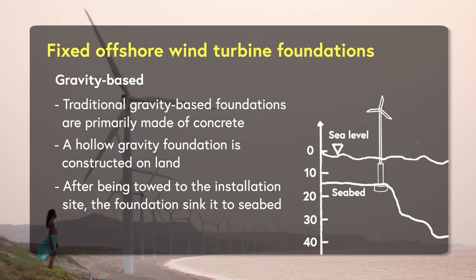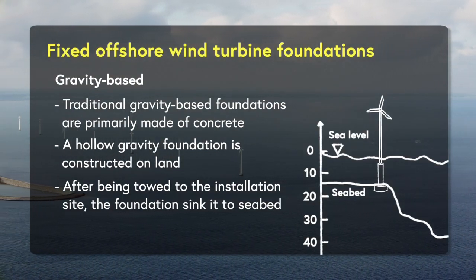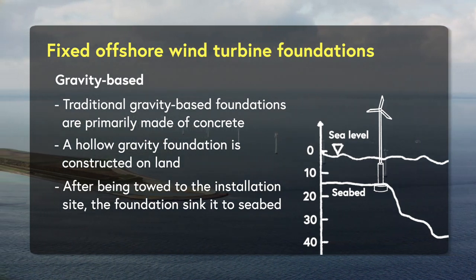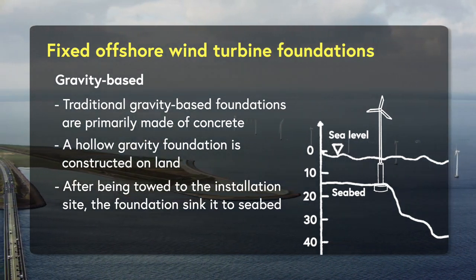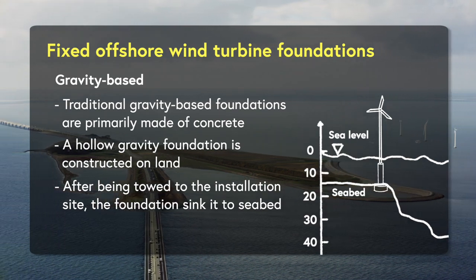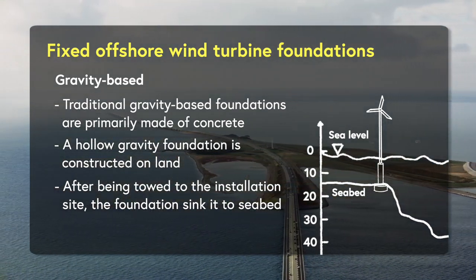So when you have strong wind, strong waves, or a strong current, you cannot guarantee that your structure on top will not move, because the gravity of the foundation may not be heavy enough. It might be dragged by the current. And another problem is the ocean current may move the sand around the foundation away, which means the foundation may not be stable when you are designing it for long-term use.